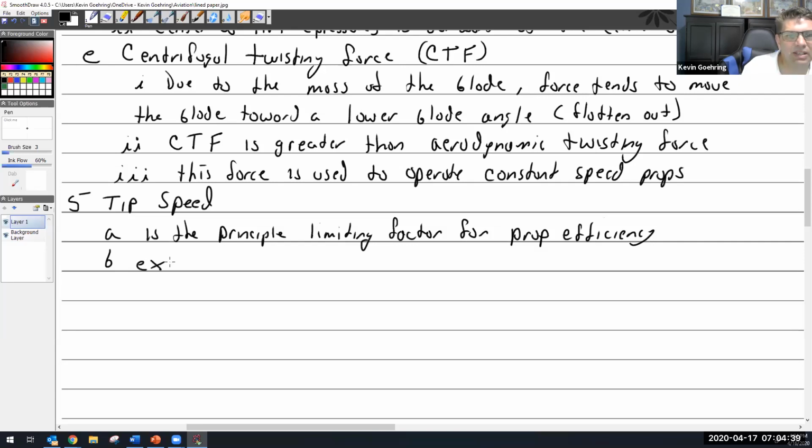Excessive speed. So I've told you before, and I think we've kind of left it hanging, that if the tip speed reaches a transonic region, not supersonic, just even gets near transonic, pressure waves are set up. For those of you that have had aerodynamics, you'll understand the pressure wave that is built up, and the pressure wave is going to cause a stall in that area.